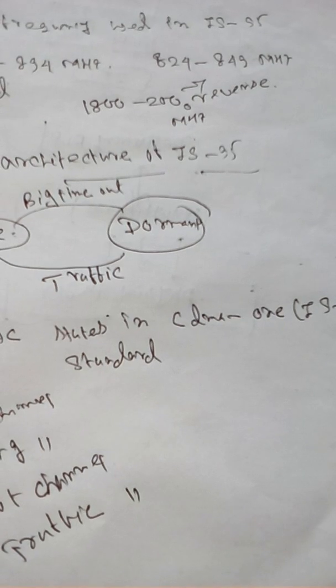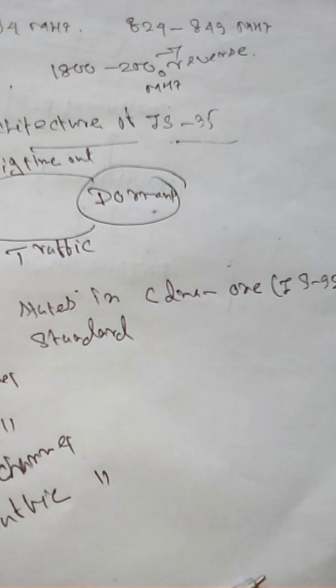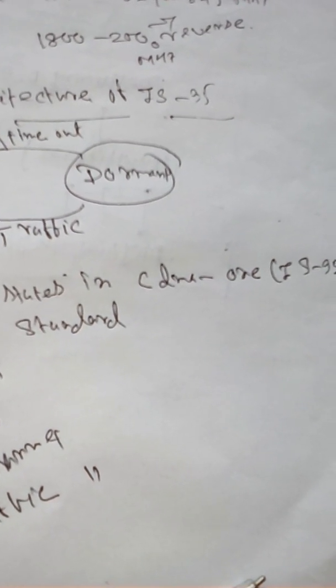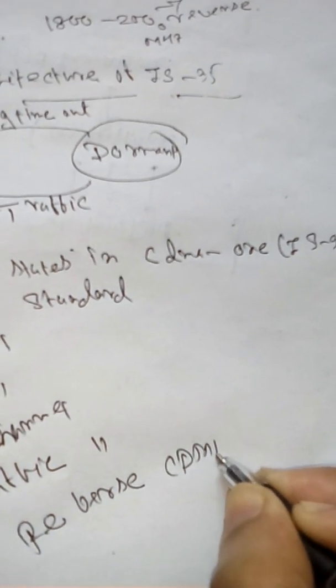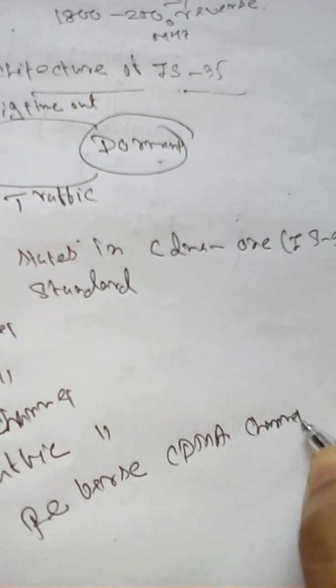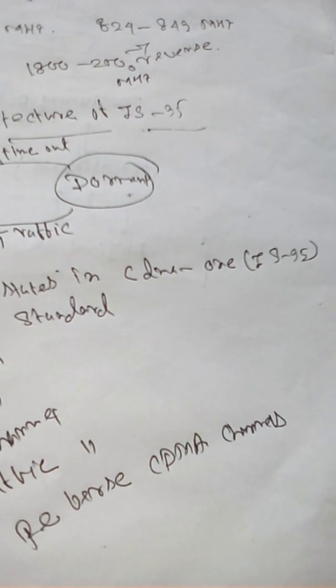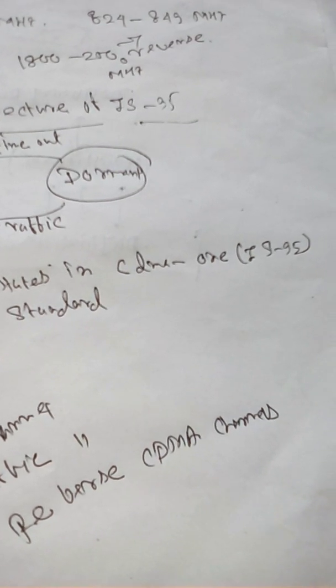Then we see the reverse CDMA channel. The reverse CDMA channels, also known as uplink channels, consist of the access channel and traffic channel. In the reverse channel, the access channels are used by the mobile station for call initiation and to provide the response to the paging message mentioned previously. The access channels can be up to 32 channels and operate at